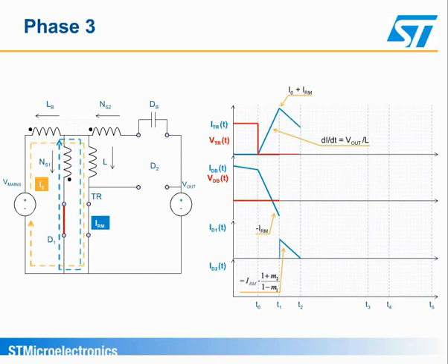To guarantee soft switching behavior of diode D1, this current should reach 0 amps before T3. During this phase, the reverse voltage applied to the boost diode, dB, is greater than the output voltage due to the serial auxiliary winding, NS2, hence the need to use specific diodes developed by ST.